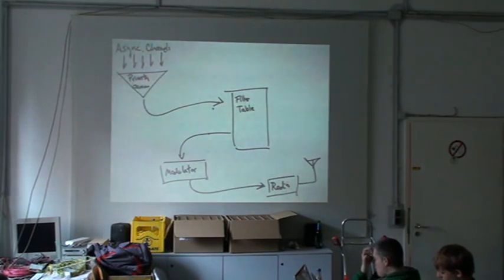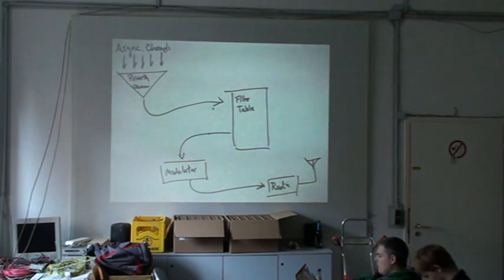If you look in OpenBTS, if you look up in layer 2 and higher up in layer 1, you can see where we exploit this in different places. For example, in layer 2, LAPDm, you're constantly supposed to be generating an idle pattern. Idle channels have to generate an idle pattern. Like on an SDCCH, you can't have dead air on an SDCCH.